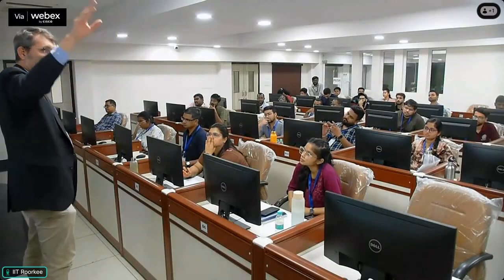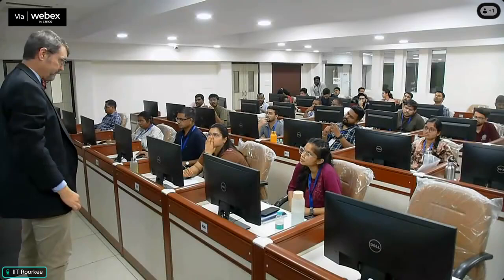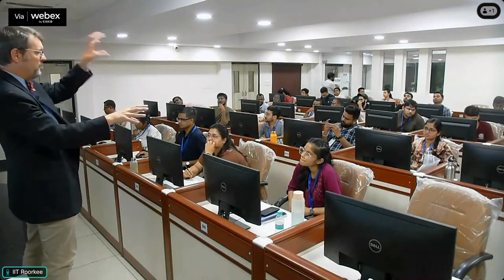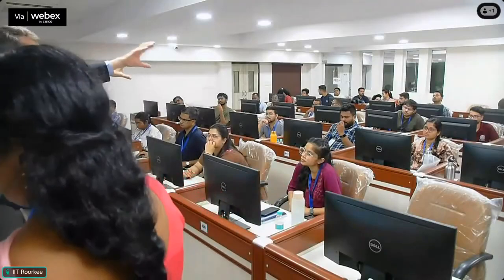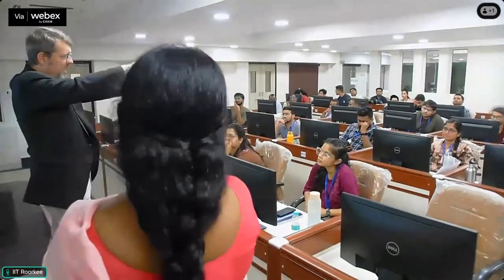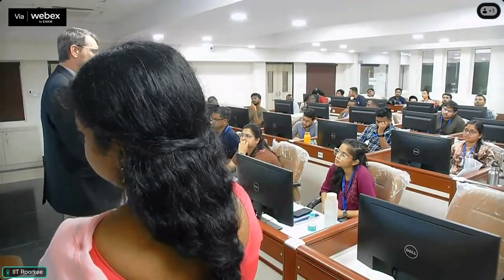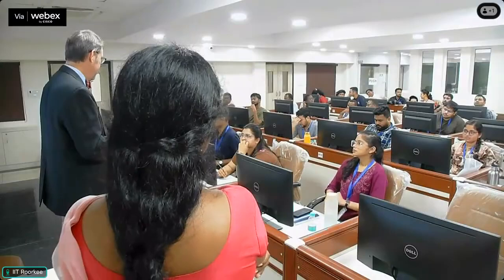Then with 30, you look at all the storms that exceeded 30. You subtract 30 from every single one of those storms, and they're going to get a difference. Then you add that difference up, and that's the amount of bypass. Then you add your bypass amount to your treated amount, and that's the total rain, which you could have just done to begin with. Then you divide your total rain by everything that you captured, and if that number is at 80%, then you've determined your water quality volume. So that's how we calculated it.